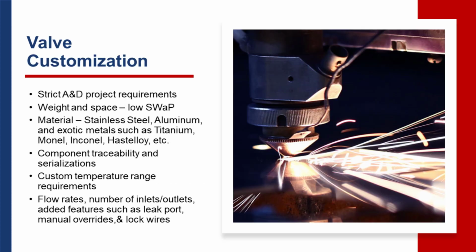Valve customization, that's what I've been doing for the past 18 years. Strict A&D project requirements, weight and space, again, coming in with low SWaP. Materials: we've worked with all of these, stainless steel, aluminum, exotic metals such as titanium, Monel, Inconel, Hastelloy, you name it. Component traceability and serialization, custom temperature range requirements, flow rates, the number of inlets and outlets, and added features such as leak port, manual overrides, and even lock wires for aviation.